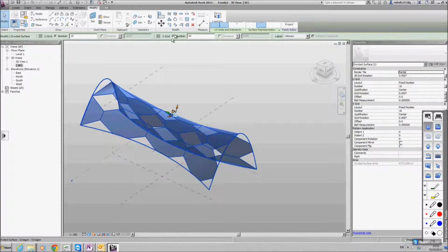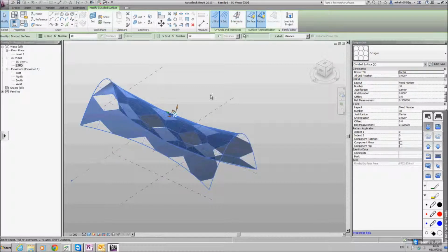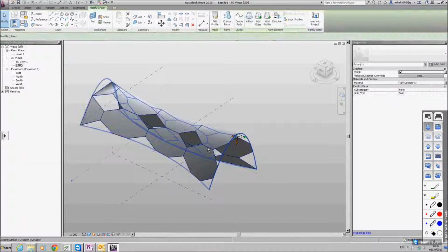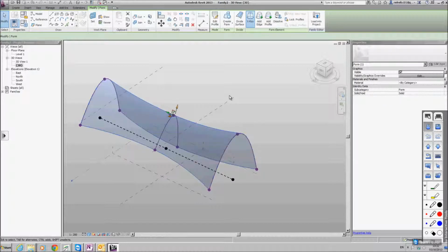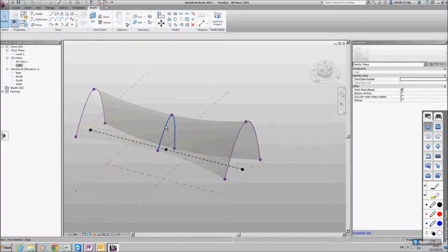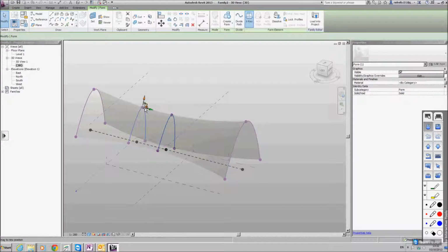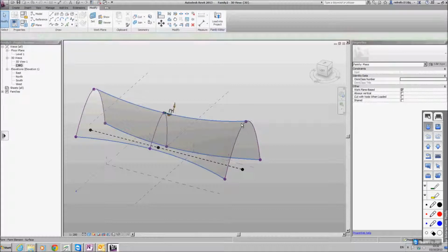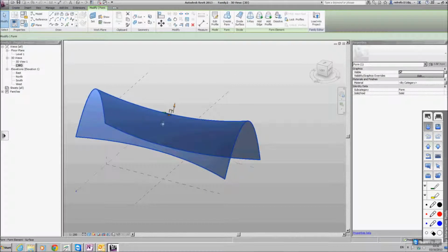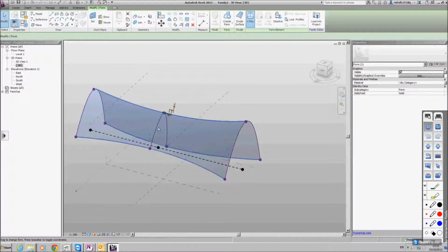We can click on it. Let me see. Just going to delete the surface of that, and now I can click on it and X-ray. That was what I was looking for, to control this center, I just have to select the actual massing shape and click on X-ray to actually see the profiles that I've used to change it.